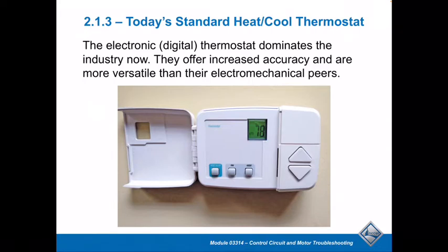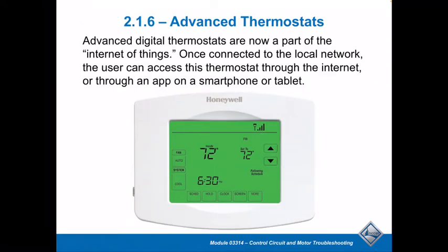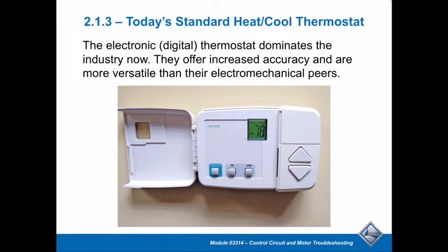Which would be typical. And by the way, on the previous one, the old standard thermostat, when you wanted, let's say, 1 stage or 2 stage, whatever it might have been, you would have had to go into the controller and program the controller for the mode, whether it's heating or cooling. You'd also have to program your cycle rate.